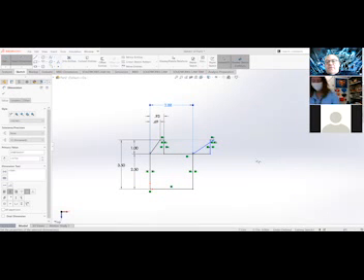So I just gave the overall width. Notice I put in 2.875, but it automatically rounded to 2.88. That's because my decimals are set to 2 and not 3. So it automatically rounds for you, which is okay for right now. We'll get into that more.